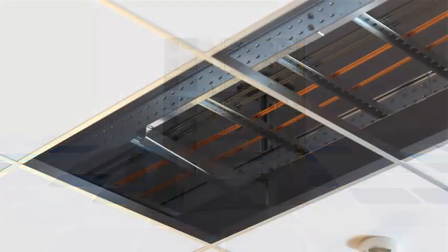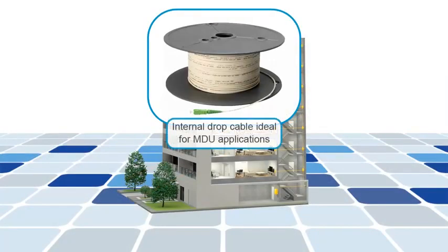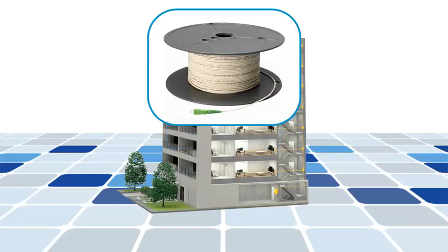These buildings sometimes have vertical and horizontal cable ducts, which already contain coaxial cables for cable networks or other supply lines like UTP cabling. Fiber optic cables may be fed through the cable ducts, and due to their physical properties, they can also be laid together with power supply cables.